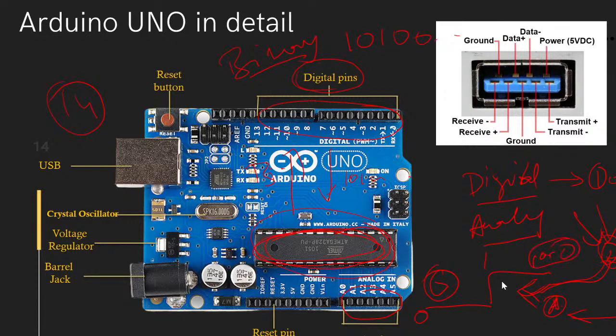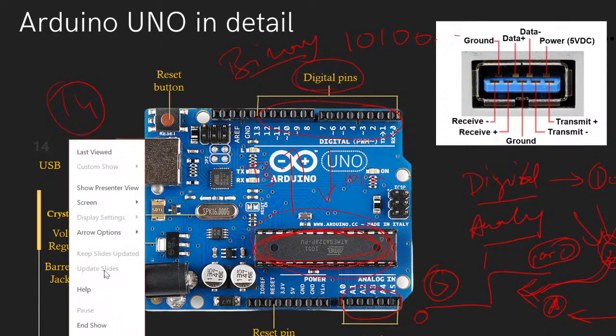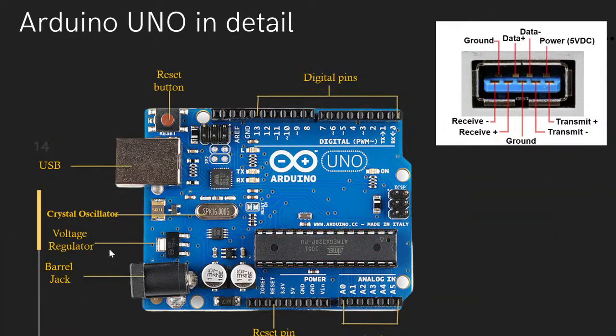It varies. If it's binary, it is only 1 or 0, but a temperature sensor does not provide 1 or 0. There are different intermediate values. That is the reason we use analog pins as input. Whatever input we give will be processed here and converted into binary code. That is why analog pins are used for input purposes.